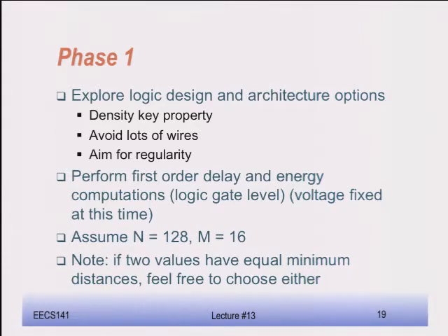That's what you're going to do first. Trying to figure out what the equations are. Write down the logical expression. Make sure that you don't get tons of wires coming out. Use regularity. Regular structures are going to be very important. That's going to give you the best possible result from an area perspective, but also from a power and performance perspective. Then we want to do first order delay and energy computation.